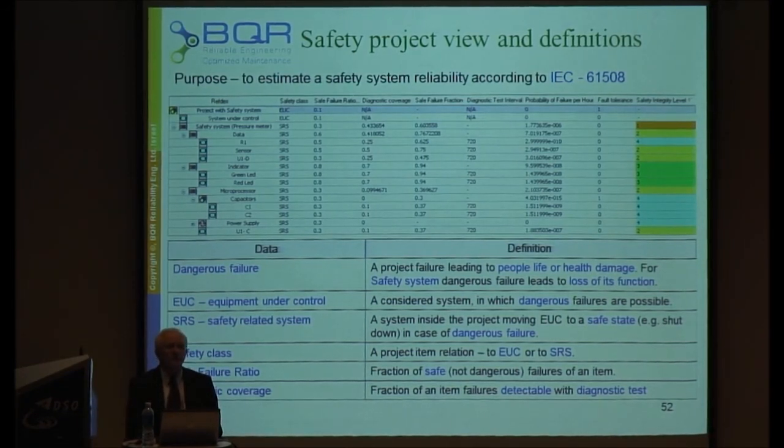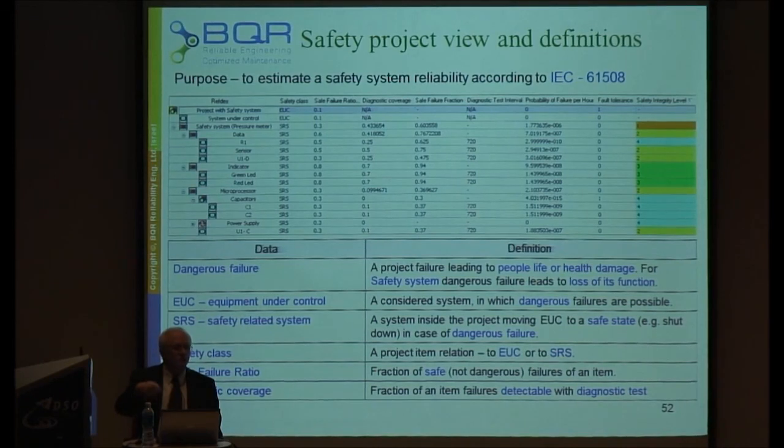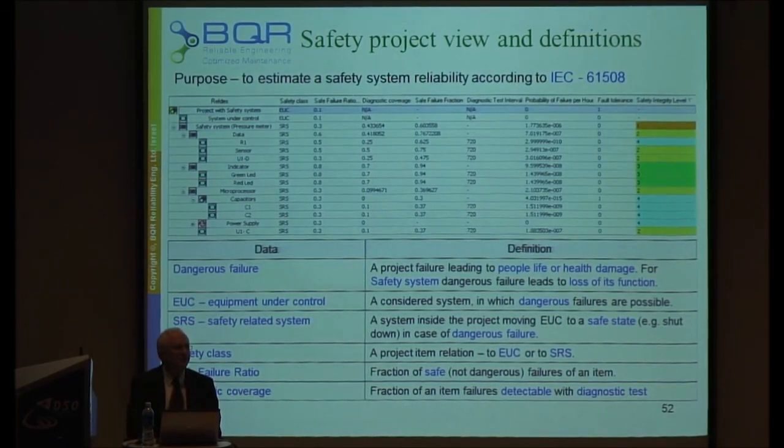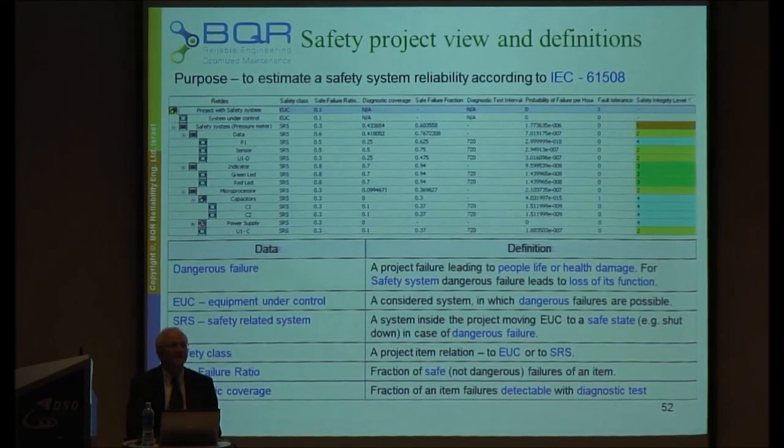The same is true of a circuit breaker in your home for power. If a child puts his finger in the power, there is a special circuit that switches off the power to the apartment, so the kid will not get harmed. But who tests this circuit? It's written in the spec that at least once a year you should go and test it. There is a special switch that you press and you see that everything shuts down.